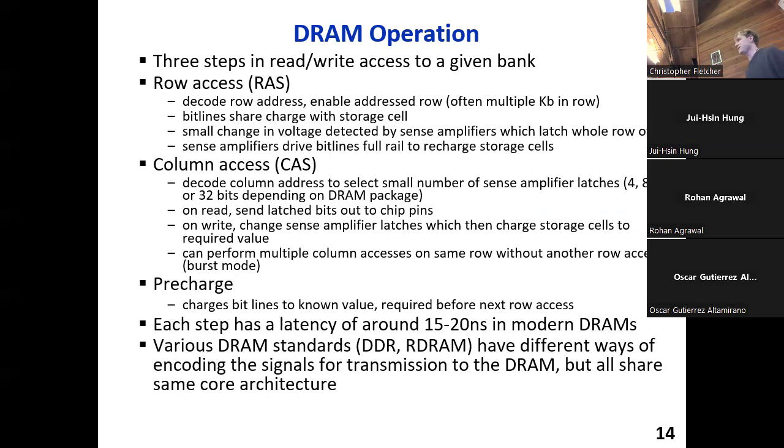You might imagine, if you think of a memory with just a flat address input, a data in, a write enable, a data out, that when you put your address in, it's atomic: you get your data out and you're done. But in DRAM, they've cleverly designed the array so that you can actually stagger how you look it up.